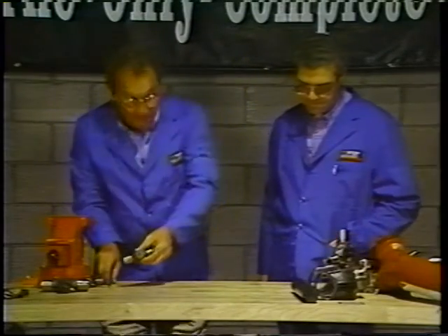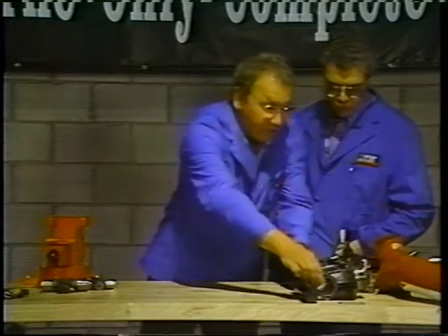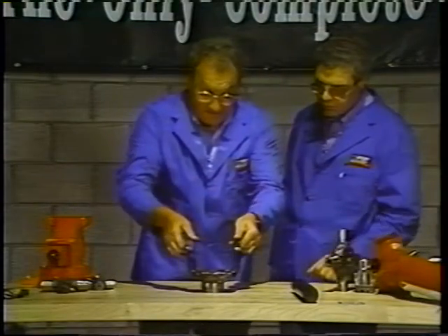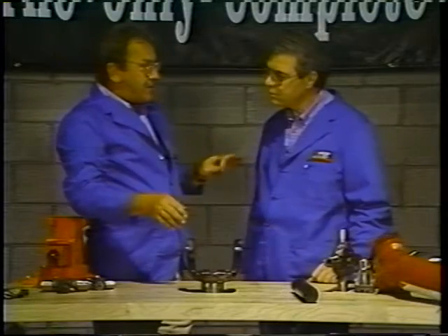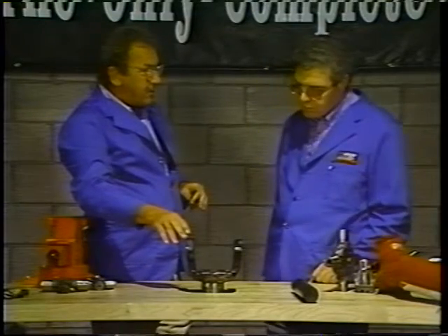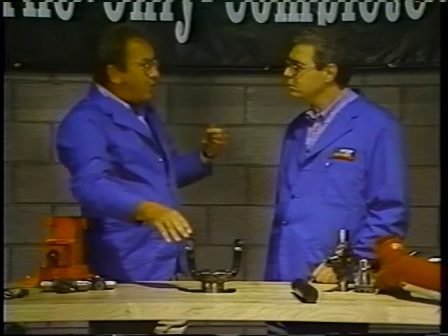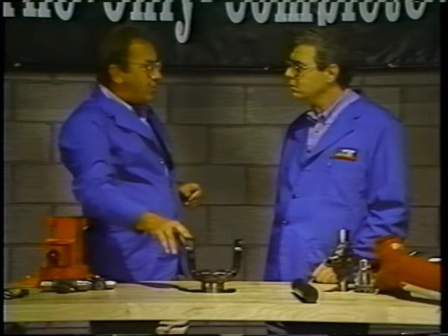Okay. Is that all we have in the area of U-joint failures? That's it. Now let's take a look at a couple of damaged yokes. This is an excellent example of a sprung yoke. Now, you see how this has been bent out of shape because of overloading? In other words, applying too much torque to the driveline caused this yoke to bend.